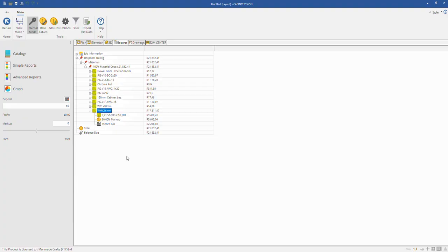Have anybody made mistakes on this, where it splits the costing out tremendously high? If your materials aren't set up correctly, if your rate table isn't set up correctly, or if your quotation as a whole is not set up correctly, or your price per board is out, then that's your material setting. If that is wrong, your material quotation system will not come out correctly. Because this one went into white melamine 16, and you see how much there is, 14.36 sheets, plus this tax.